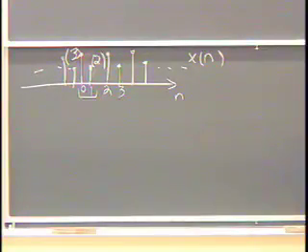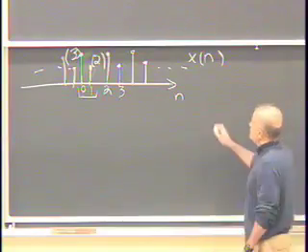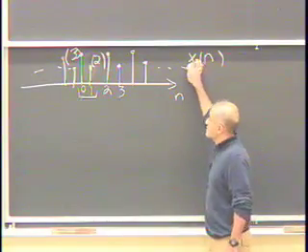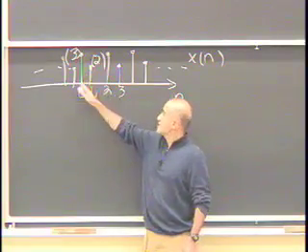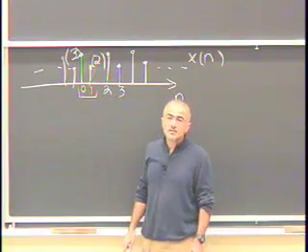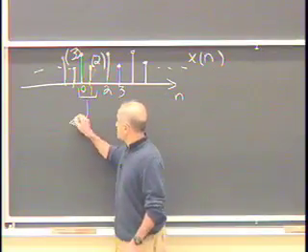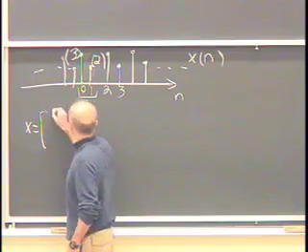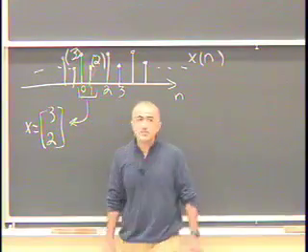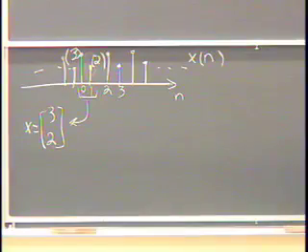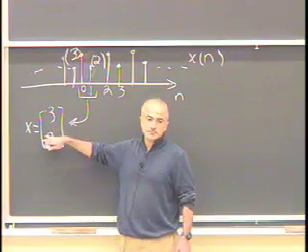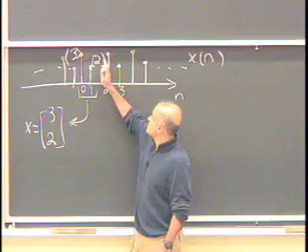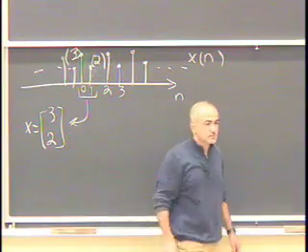We said we can use the same principle when we look at periodic signals in discrete time, because when I look at a periodic signal in discrete time, in this case with period 2, I can stack up the values of that signal in a vector that I call x, 3, 2, exactly like the vector I have there. And all the information about the signal is embedded in this vector. There's no additional information that the rest of the periods give me.